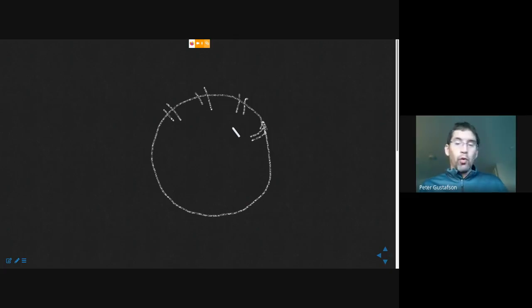How do I know? Well, because this is a torsion problem. We have stated that we have a torque T. We said we're separating out the bending components that would be a shear resultant. So there is no shear resultant in this problem. It's only a torque. And so consequently, the integral of all the differential shear components has to be equal to 0.